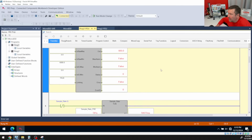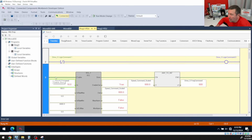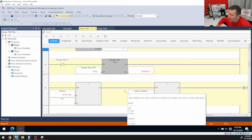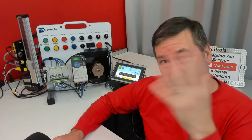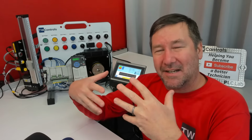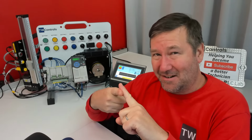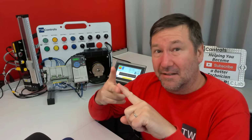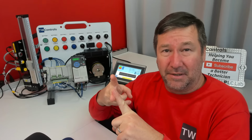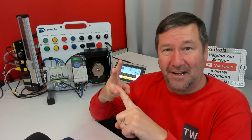So that gets us where we can have our speed command out of our PID. That's going to be in percent. And then we're going to get our feedback in RPM. Next one, we will actually go through adding the PID instruction in, piecing it together. More importantly, I know everybody just wants the PID to work, but figuring out our sample rate, figuring out a wind-up issue very specific to Connected Components Workbench, then how to auto-tune it.